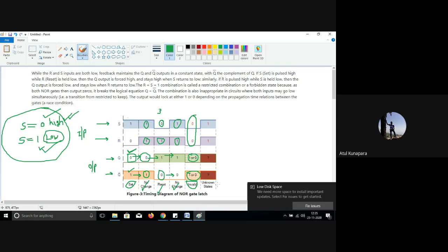So are you getting how this timing diagram is going to work? See, in this timing diagram, on the x-axis we are taking the time, and on the y-axis we are taking the condition of that signal, whether it is logic low or logic high. Based on that, you can predict and find what the next output will be. So you have to look at the previous input also. In the timing diagram, each section is considered to be a span of 1 clock cycle.